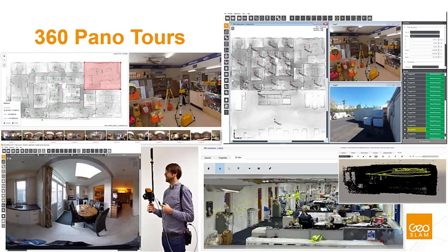We're also able to integrate these pano images into some third-party tools. There's a couple of different opportunities out there to do that, but the one I'll note here is an application called Context Capture. Context Capture is owned by Bentley Systems. Basically, in Context Capture, we can bring in our point cloud as a universal file format, and then we can create a mesh of that point cloud.